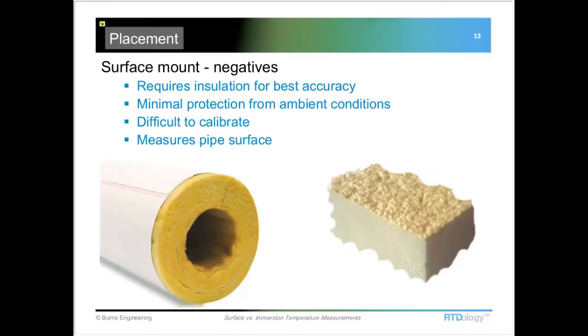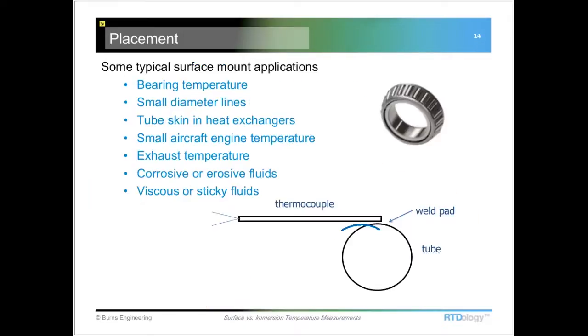so that you don't go wrong, just because of the expansion and contraction of that casting when it gets up to its operating temperature in the machine that it's going into. You need to start out at maybe a little different tolerance to be able to hit the final tolerance for that part. And doing some kind of a surface temperature measurement will enable you to better hit those tolerances.